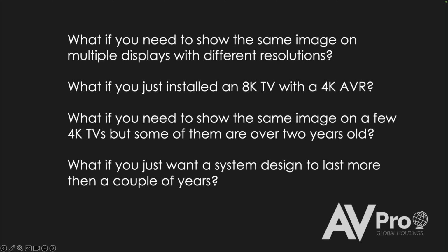What if you need to show the same image on a few 4K TVs, but some of them are over 2 years old? This is something we're going to jump into today too. 4K TVs are not all equal. 4K talks about the number of pixels on the screen, but the resolution comes from the signal. And the signal with HDMI has changed quite a bit since 2017 when 4K TVs first came out.